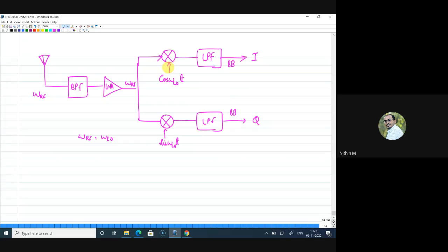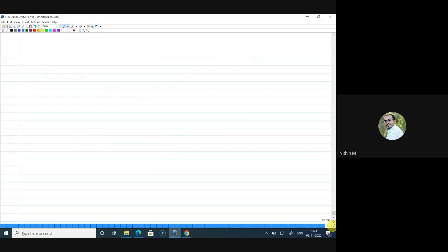The reason this DCR, direct conversion receiver, is simple is because of the smaller number of filters that we were employing in all the previous architectures to remove images. So that is a great relief when you look at it that way, right? But nonetheless, there are issues, and we may look at the issues of the direct conversion receiver now.